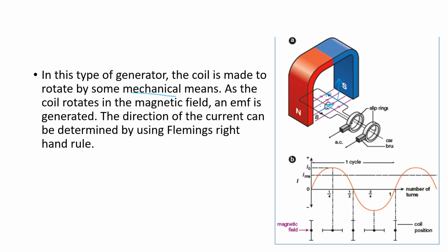Once you have located your magnetic field going from north to south, and realized that the current in the straight piece of wire is going into the board or into the paper, you would see that your thumb is pointing up. So what it tells us is that the wire is going to move up. But let's consider what is happening on this other side of the coil. On this side, our current is perpendicular to the magnetic field, which is wonderful because that's what we want.